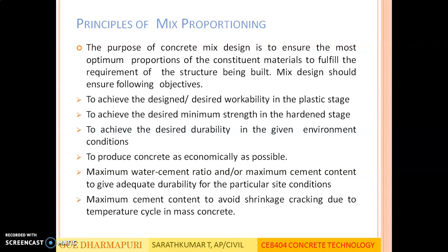Mix design should ensure the following objectives: to achieve the desired workability in the plastic stage, to achieve the desired minimum strength in the hardened stage of concrete, to achieve the desired durability in the given environmental conditions, to produce concrete as economically as possible, maximum water cement ratio or minimum cement content to give adequate durability for the particular site conditions, and maximum cement content to avoid shrinkage cracking due to temperature cycle in mass concrete.